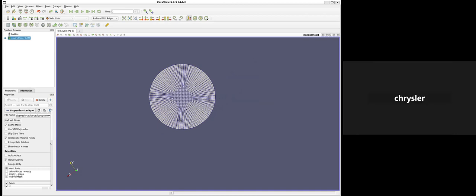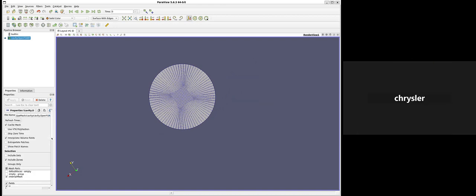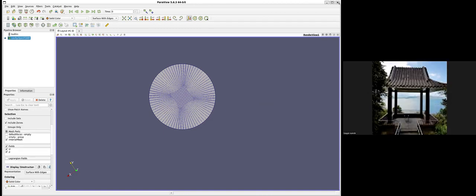You can make the mesh finer by increasing those numbers. Close this, and go into your blockMeshDict. So I have to go to the blockMesh text. Yes.